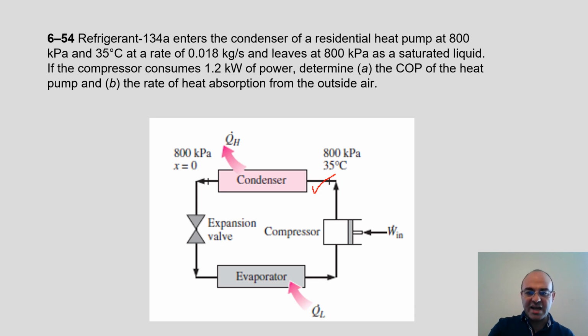So here there is another chance to review the components of a refrigerator, which are the same as the components of a heat pump. A refrigerator has a compressor that compresses the gas, so its pressure and temperature increase. Then it enters a condenser in order to give away heat, Q.H., to the surrounding.